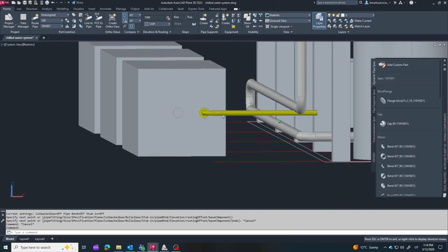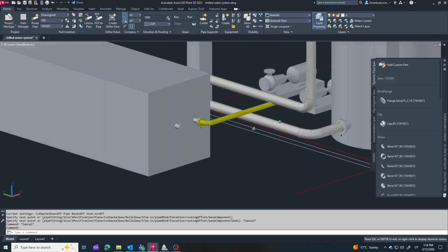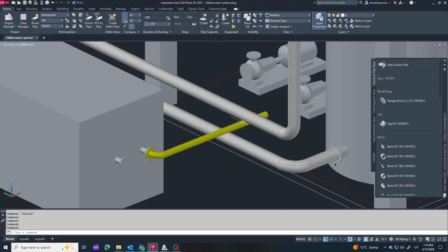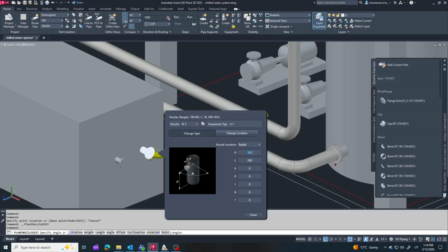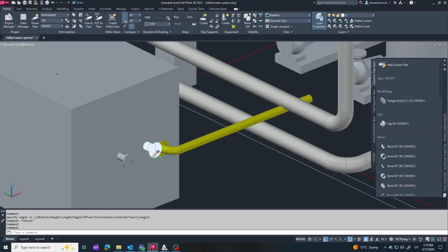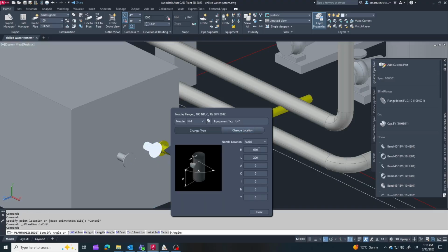The refrigerant is then compressed, and the heat it absorbed is rejected to the surrounding air through the condenser. After that, the refrigerant expands and the cycle repeats. So the chiller continuously takes heat from the chilled water loop and releases it to the outside environment, keeping the system water cold.